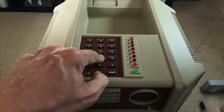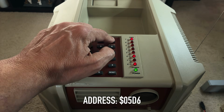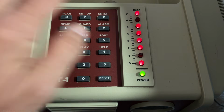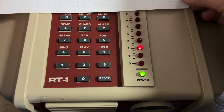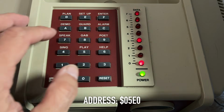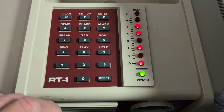And now for the moment of truth. We run the program at address 05D6 and... Hello World, ready. Well, that wasn't too shabby. And because of the way we structured the program, with the phrase data starting at a fixed location after the code, we can change the phrase to something new by just running the F5C4 bootloader at the 05E0 address instead of at 05D6. I wonder what these numbers say.